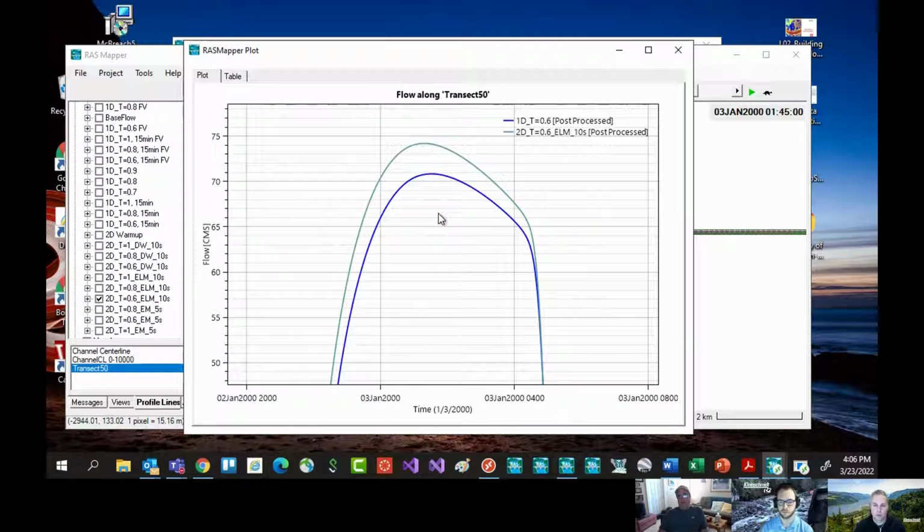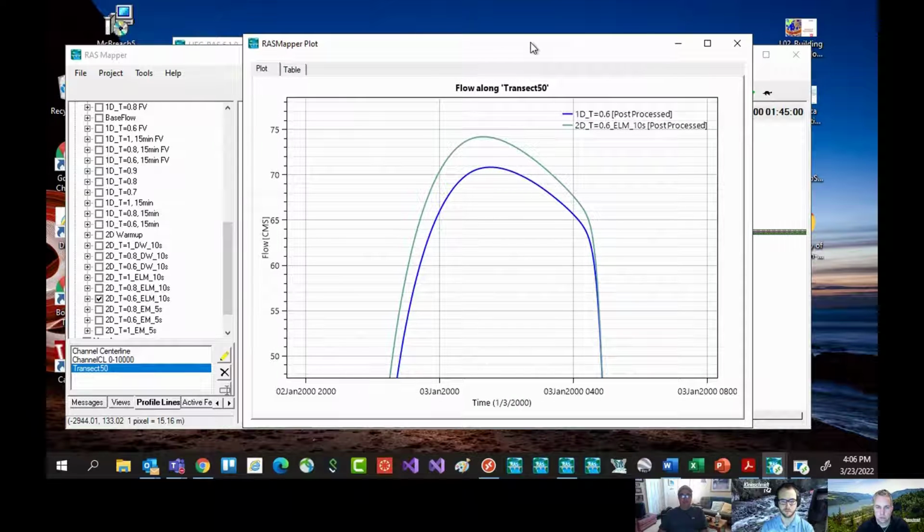Okay. In most real world models, rainfall runoff and so forth, you're not going to see much, especially as you make the cell size smaller and the time step smaller. But where it does start to show up is in these difficult problems that are highly velocity driven. You'd also see it, for dam break floodways, you might see it a little, but real tight contractions and expansions where you have rapid changes in velocity versus distance.